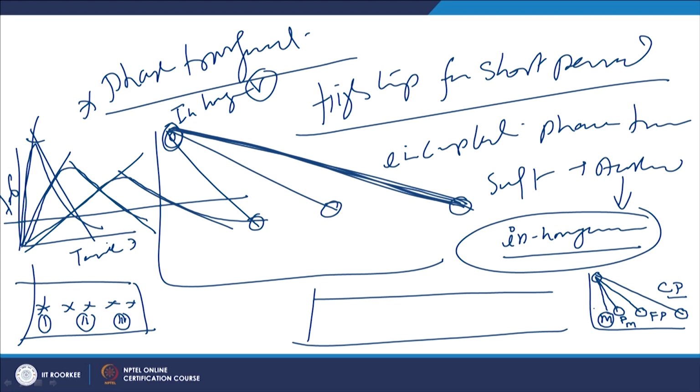Since each phase has a different microstructure, different crystal structure, different mechanical properties are offered. The coarse pearlite will be the softest, then somewhat higher hardness, then further higher hardness, and the maximum hardness will be offered in the case when the point is very close to the fusion boundary.